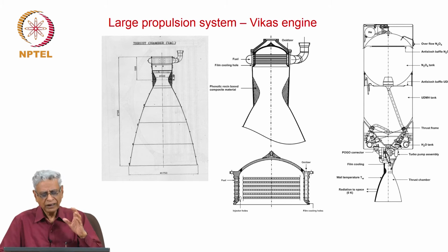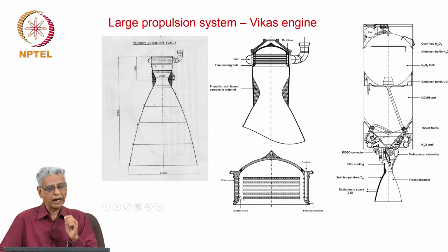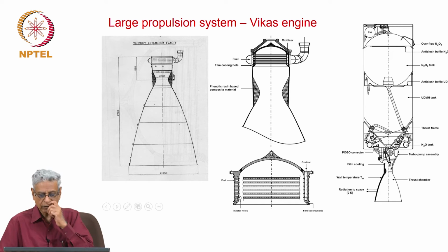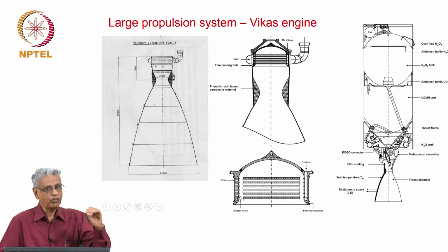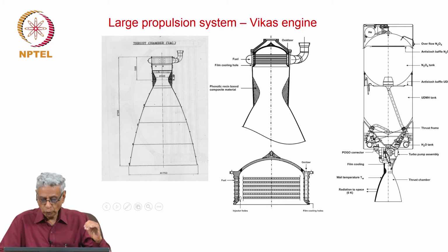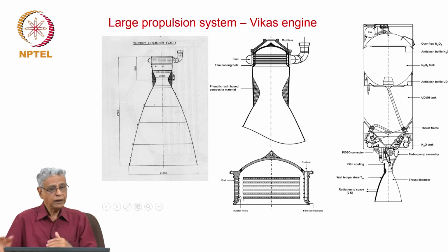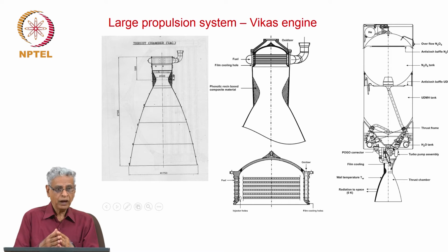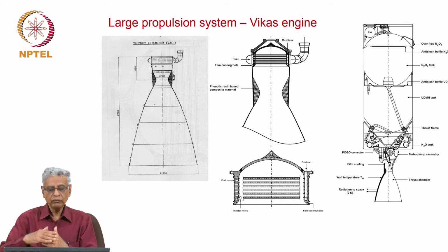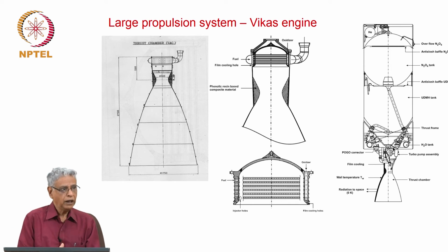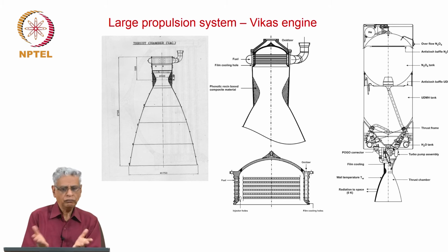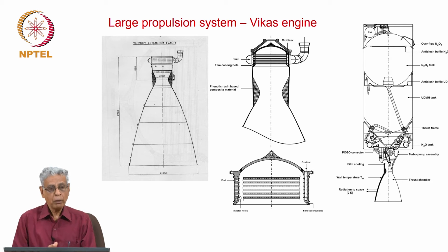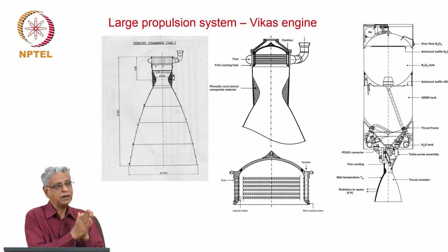It turns out that you must treat them as flexible elements. And if you do not design this pogo corrector properly, you will discover on occasions that there are pressure fluctuations of low frequency which get coupled to the structural system, and this becomes amplified and the whole vehicle can get into difficulty. It does not happen with this vehicle anytime, because the pogo corrector has been designed properly.